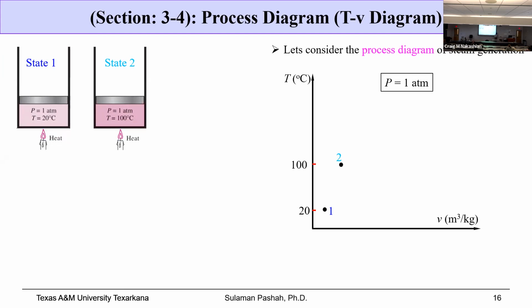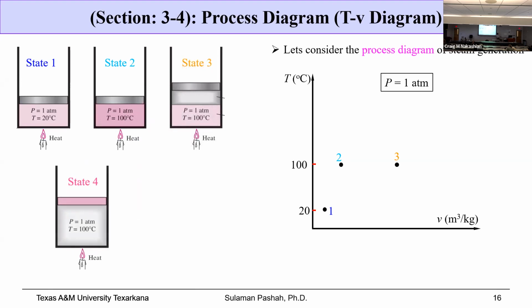And then I know that once the boiling starts, after that, the only change will be volume, because the water is converted into gas, so the volume will be increasing, but keeping the same temperature. So the next point will be on the same temperature value, until you complete your boiling process where there is no more liquid and you have entirely a gaseous state, and the volume from here to here has increased considerably. So from 2 to 4, it is just the increase in volume, keeping temperature constant.